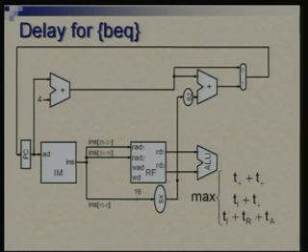For branch, there are three paths I need to consider. One goes through both the adders, so T plus and T plus. Another path goes through TI, the instruction memory, from where we are picking the offset and then adding it to PC plus 4. So it is TI plus T plus. And the third one where comparison is being done is TI, TR, and then TA. So whichever is the largest of these will dominate.